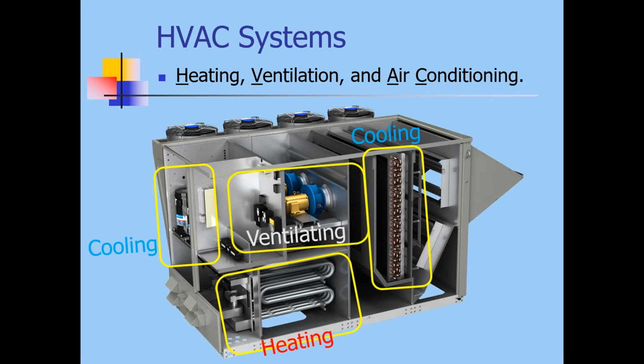Lastly, we also have the ventilation section, which consists of a blower and a blower motor and provides air circulation for the entire building. It will pull the air from the building through both the evaporator coil and past the heat exchanger.